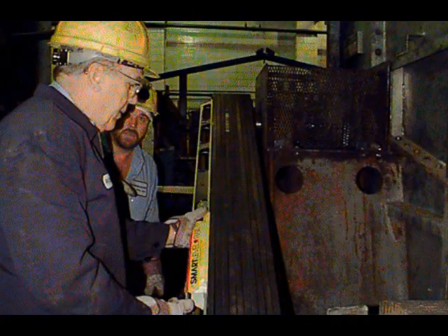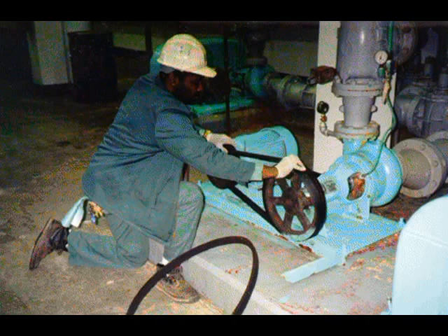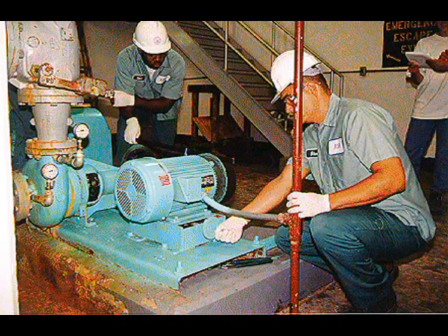When installing or replacing V-belts, the motor and belt sheaves must be aligned. The belt must run straight between the two sheaves without any angle. During belt installation, belts should not be forced over the sheaves or over the sides of the grooves. This can damage or even break the belts. Before installing the belts, loosen the motor to bring the sheaves closer together. After the belts are in place, the motor is pulled back and bolted in place.